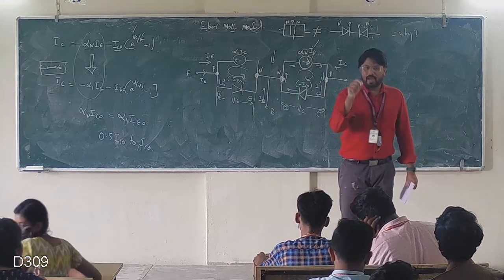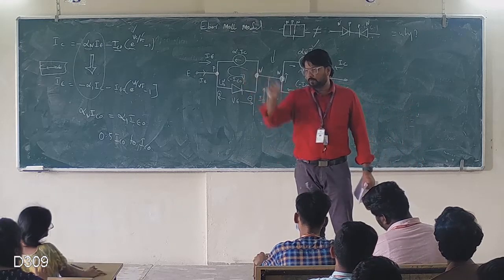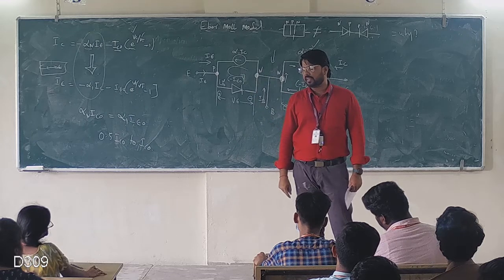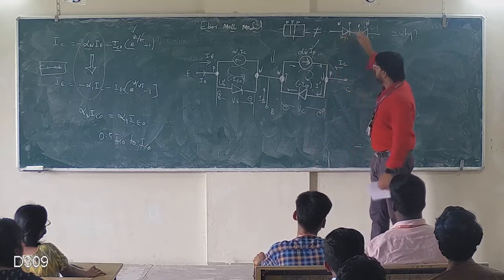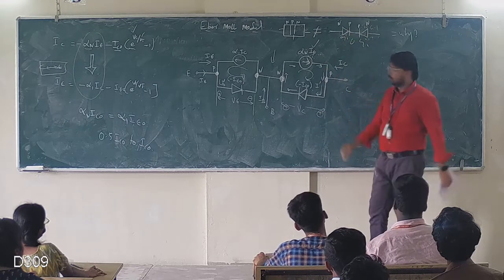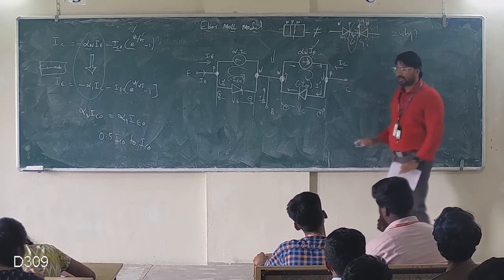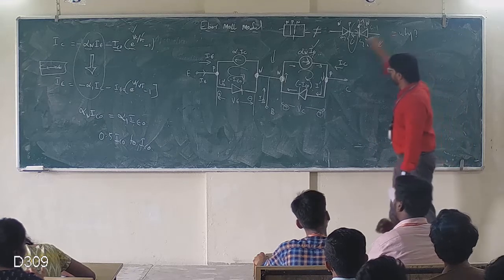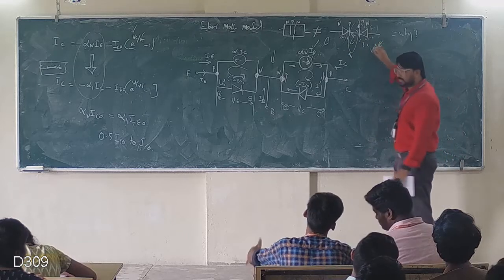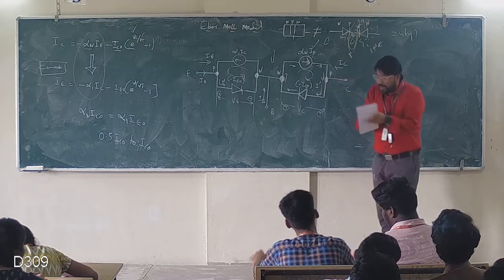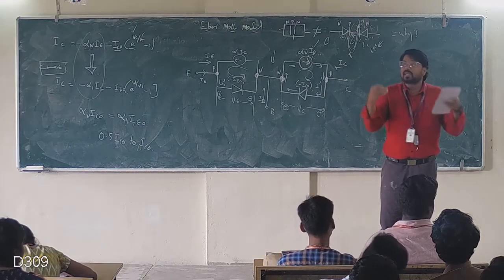I would say 100 electrons may start from the emitter, 99 reach the collector, and only 1% is retained in the base as recombination. But with back-to-back connected diodes, the base is a conductor. What about a conductor? Recombination is 100%. Let us say a back-to-back diode cannot be a transistor. Why? Let us say this is emitter, collector, base. Let us assume back-to-back connected diodes. If 100 electrons start, 100 electrons recombine, or are stored at the base because the base is a conductor.